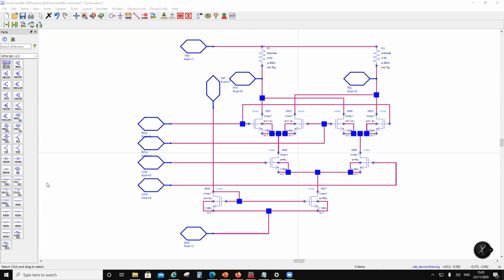Other than that, I haven't touched any models. For example, using this transistor as a varactor, I have used that and found it very crappy. Rather, just use a transistor and do the connection, and that's it. So what I'm going to share is a PDK where you can use only NMOS, PMOS, inductors, capacitors and resistors. Other than that, I haven't touched any of this stuff.